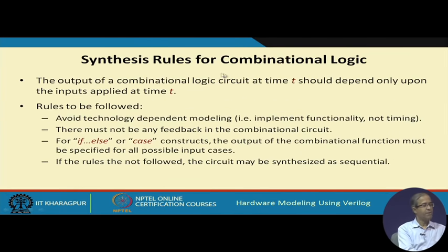So, talking about the synthesis rules for combinational logic, you recall what we mean by a combinational logic? A combinational logic is a hardware circuit which does not have any kind of feedback or storage devices built into it. So, the output of the circuit will only depend on the currently applied inputs. Of course, the gates will have some delays, so the output will be available just after the circuit delays.